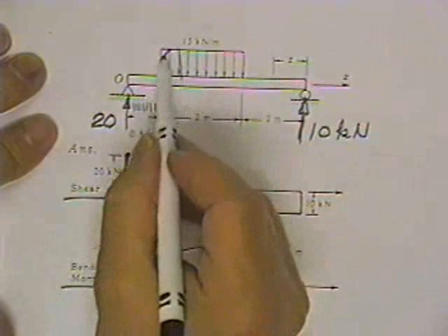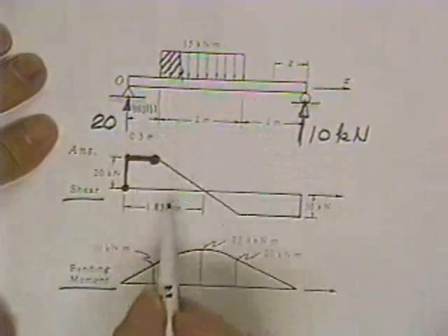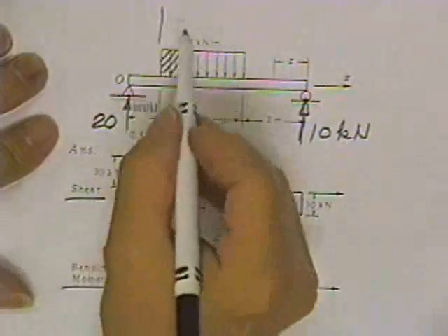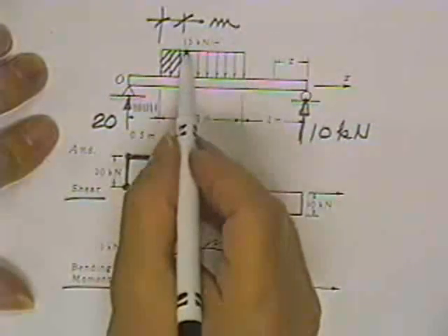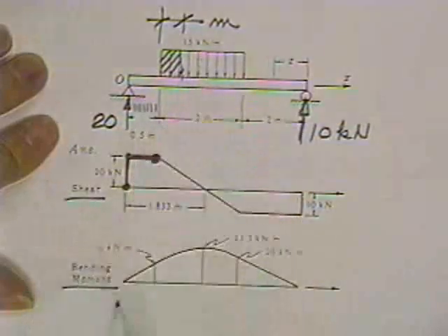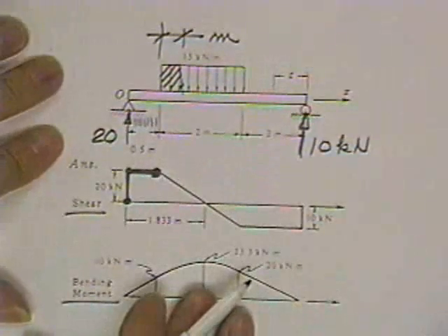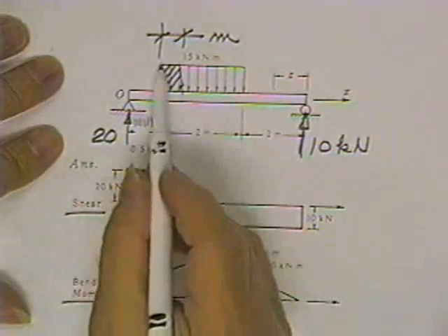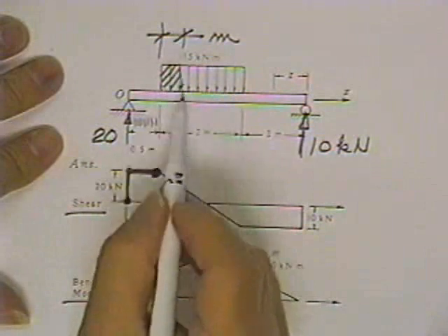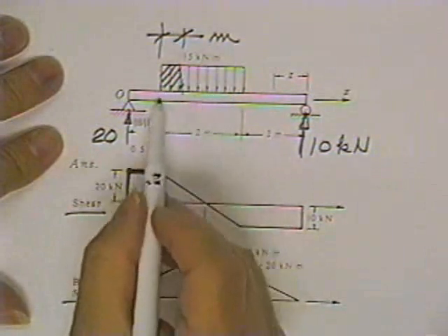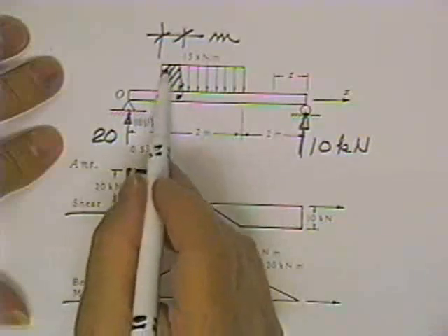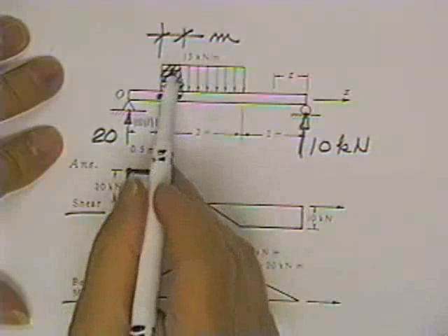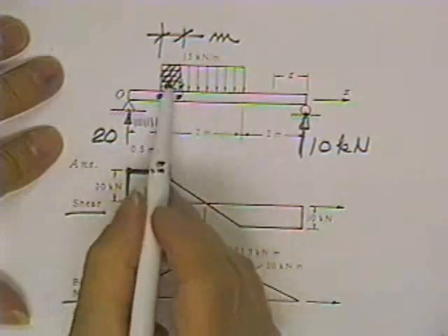Now these loads, on the other hand, are not concentrated loads. These loads you would have to move a whole meter before you would pick up 15 kilonewtons of load. It's like sugar bags stacked across the beam. And therefore this load doesn't say go down 15, go down 15, go down 15. It says start here, and as you move 1 meter, you will cross an area, and that area will tell you how much to go down.